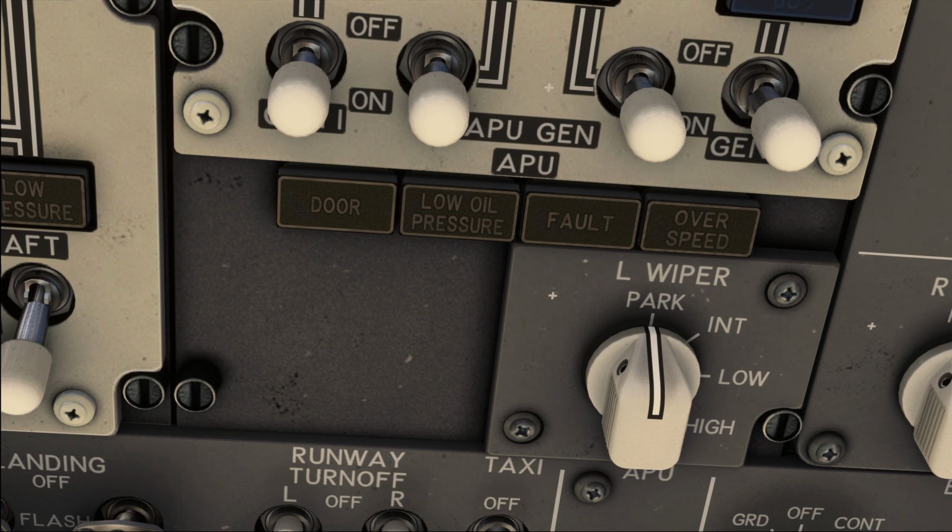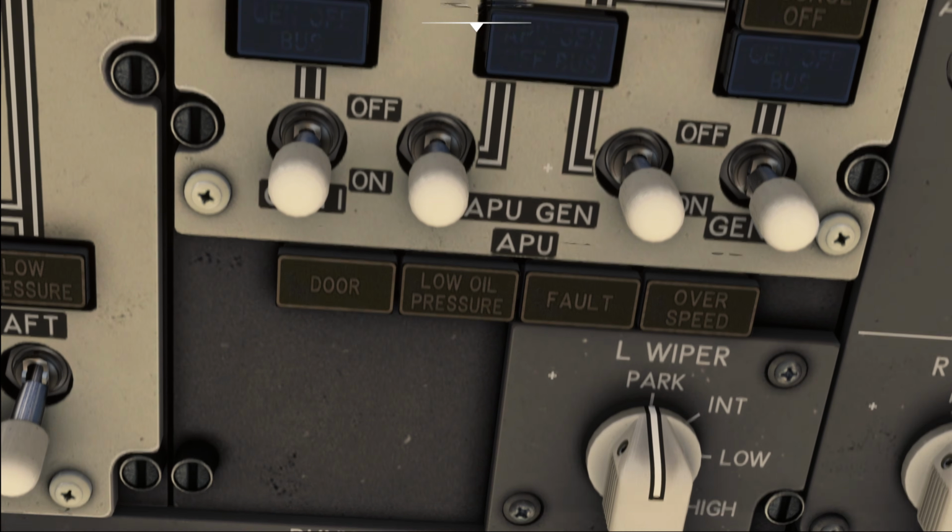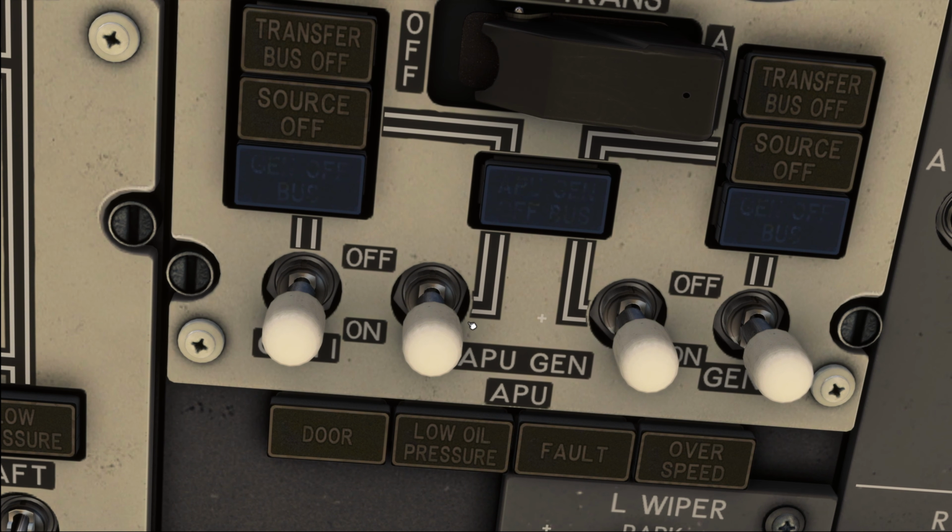Now, apart from that, there is a new operational consideration there as well, and that is due to the new shape of the LEAP-1B engine. Some engine components have been redesigned to fit around the new structure. The operational impact can be seen in the QRH when you're operating again on a single AC power source, as we have talked about earlier, and this includes just operating on the APU generator.